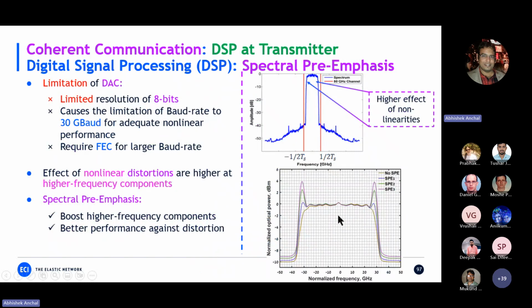So what happens when a signal is passing through a filter? The filter has limited bandwidth and sometimes is shifted from the ITU grid, and because of that, it cuts the side of the signal. Most of the carrier clock synchronization information lies here. So it cuts the signal, and we get bit error. So how do they emphasize it? The amplifier is going to reduce the power at the edge, so the best way is to increase the power at the edge.